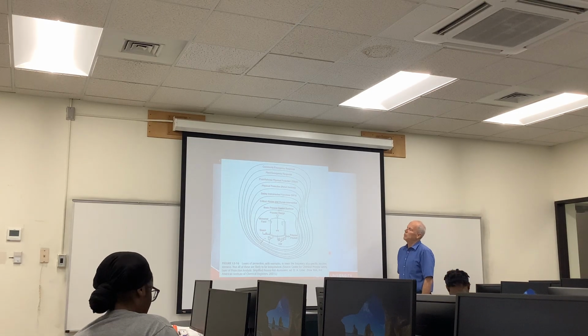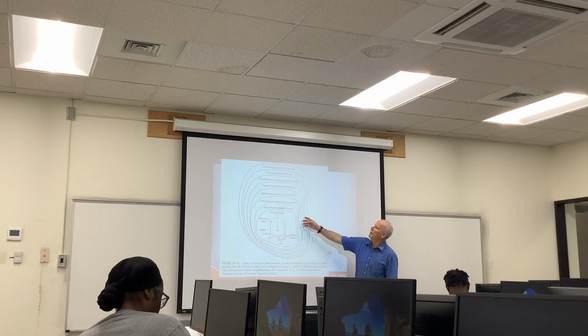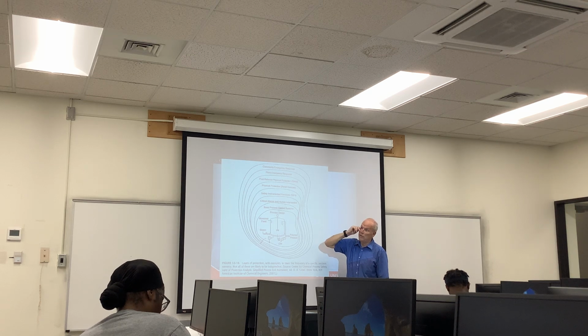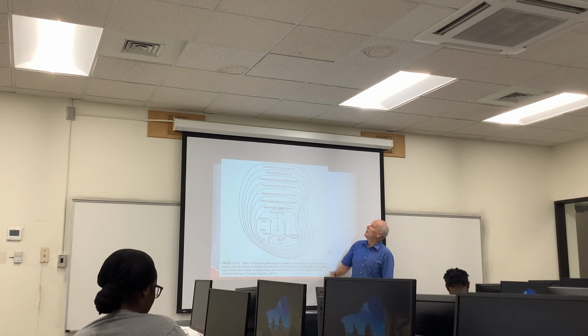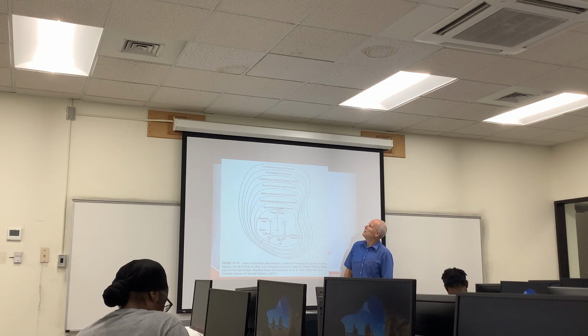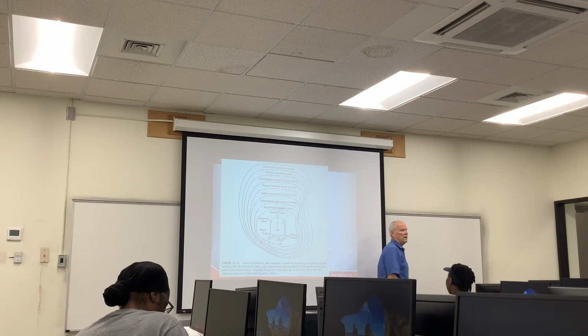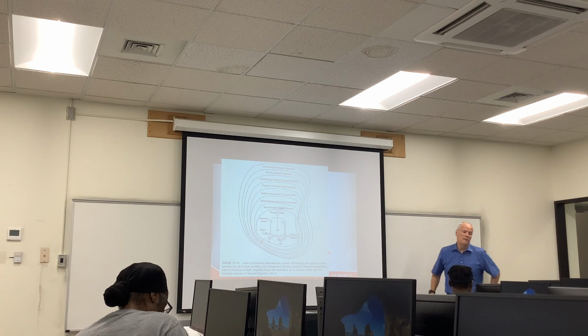Take credit for your basic process design, then you can take credit for the basic process control system, you can take credit for alarms, unless they're part of the control system, in which case you can't take credit twice because they're related to each other. Then you've got your safety instrumented functions, your physical protection, and then your other physical protection. Relief devices would be active type devices, and then dikes would be not active. And then you've got your response.